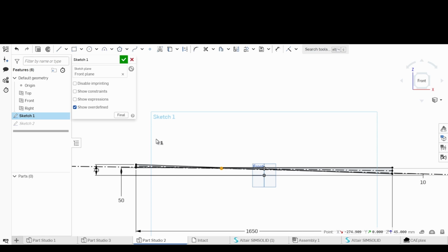It's not exactly accurate because it's not truly dynamic. It's using two static points to find it, but it's given us an idea of where the actual roll pivot is compared to the roll center. And I'll show you in the Excel of roll center compared to these different locations.